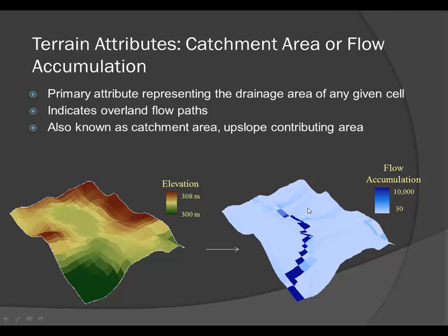So we're getting an idea: water's moving down this slope, this aspect, and it could be characterized showing the plan or the profile. And as we look at the very, very large numbers of flow accumulation, you can see where water is collecting on the landscape to a significant level to form a stream or a rill or some sort of conveyance that we could observe on the landscape.